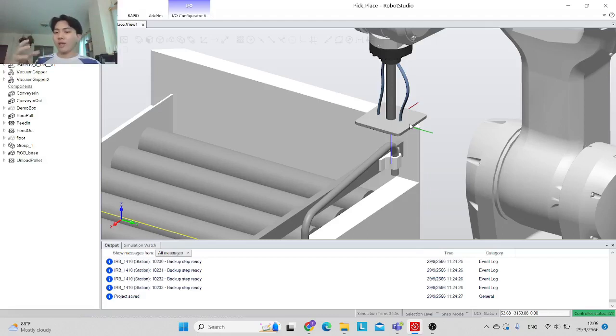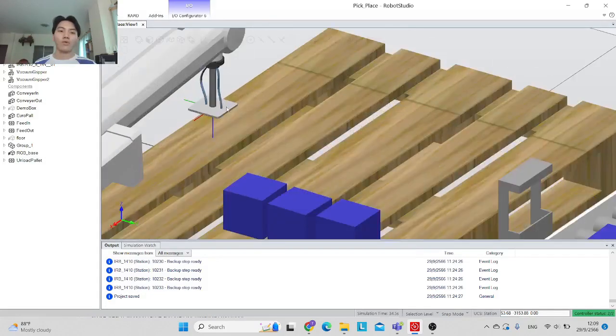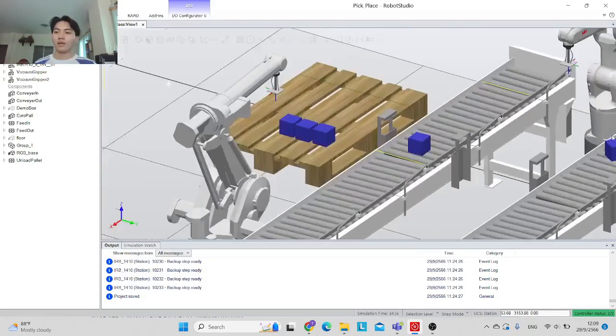Instead of grabbing with a gripper or hand, we can use the vacuum, like a pneumatic system, to vacuum the thing. It's easy to change, easy to use, and easy to apply on the end effector of the robot. We use this in robotics.